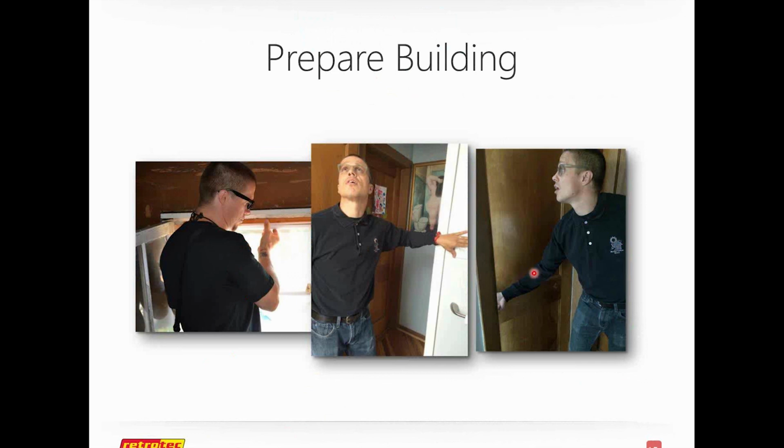We also want to open all interior doors, and sometimes you will have interior windows. So here we have our energy auditor opening up the interior doors, and the reason for that again is that those interior doors can actually shut off the outside or part of that house and we want to test all of the house. One of the great things about a blower door test is that it tests the entire house, the entire shell at the same time. And here we have the auditor turning off the furnace, turning off any interior fans, and just got a little story here from one of our friends out there.